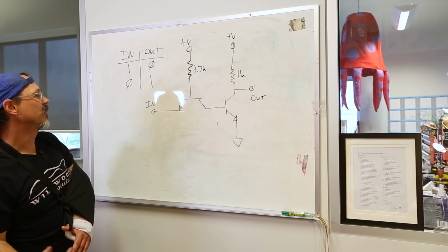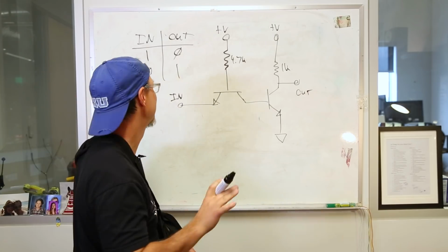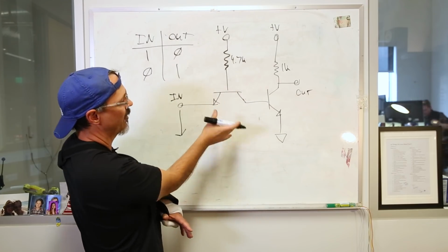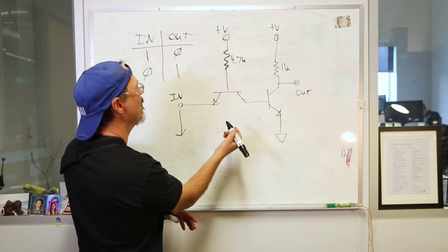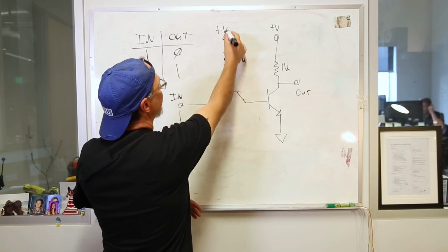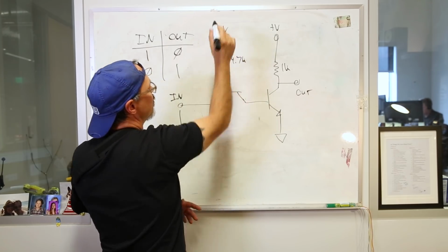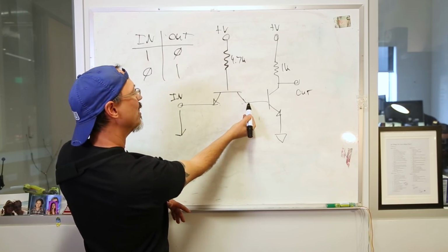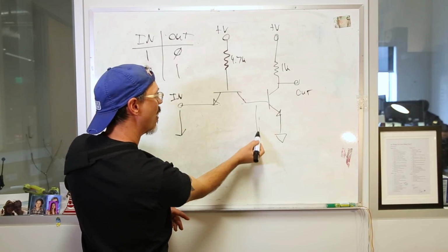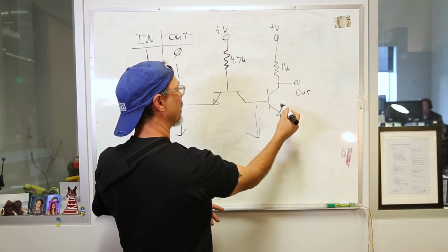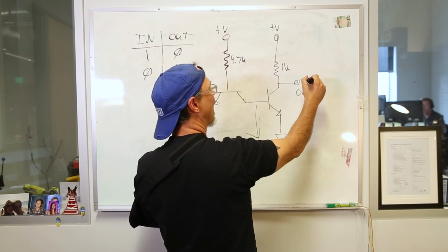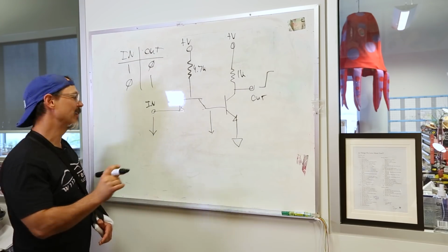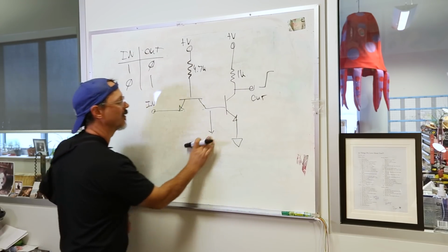Now, the way this works electrically is like this. When you pull this guy low, kind of turn this thing 90 degrees in your mind, you've got a circuit that is base current up to your positive voltage, okay? And when that happens, this turns on and it pulls this guy's input down, all right? Turning this off, so this becomes a high resistance, which makes that a high. Low equals high, okay?